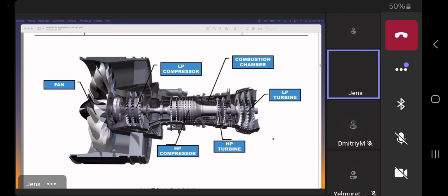Yes, depending on the speed you travel, you're right. But the best point is, we have a bypass ratio up to 100-to-1, so very, very high bypass ratio, and that makes the turboprop engine most effective at low speeds, as you said already, 0.6, 0.7, depending a little bit where you read it, and the handout mentions 0.7 as the speed.